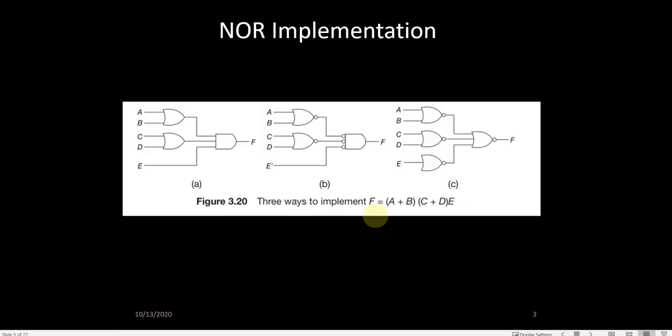Right. Okay. This is NOR implementation. In case we are grouping zeros for an expression, we will get it like this, right? That K map is not shown. From the zeros, if we do it, OR AND application, from the max term we'll get this initial type of gate. So to make it NOR, we are going to put 2 bubbles here.